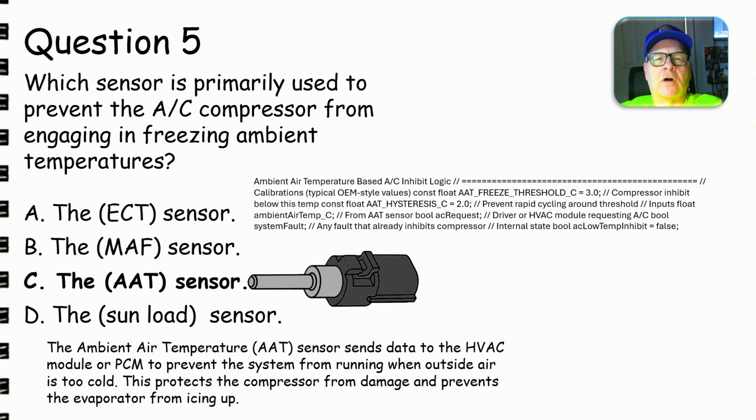The GM cars, back when they had the computer command and control feedback carburetors, what they would do if they detected an overheating engine was they would basically release the mixture control solenoid in the carburetor so it would be up all the way. When it was energized it was down, when it was de-energized it was up, and it would let it run a little richer, because when it's running richer it's running a little bit cooler. Now that's not going to save one that's seriously overheating, but it'll help it run a little cooler. All kinds of strategies like that.